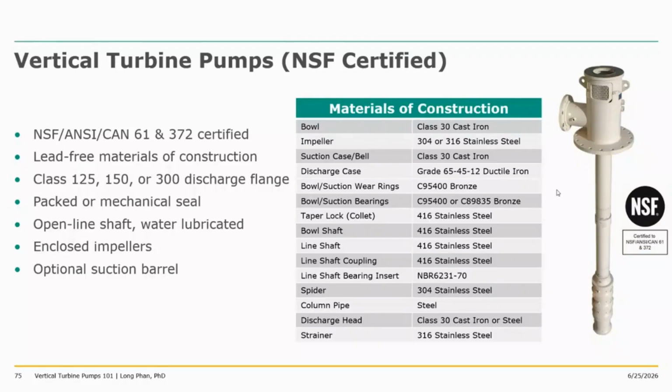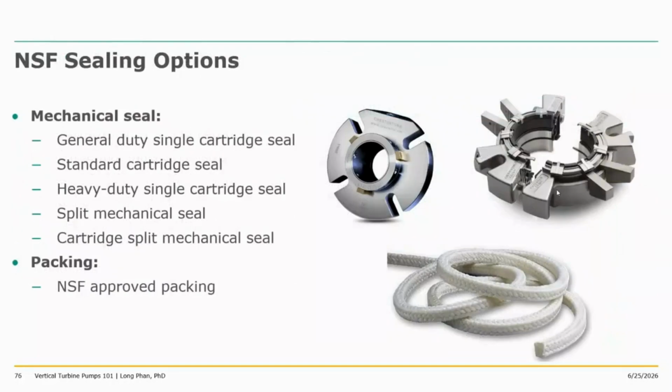Mostly you see stainless steel, which is safe for potable water, or any lead-free bronze. And if you have cast iron or steel in touch with water, you will have a special NSF certified coating for it. And vertical turbine pumps, NSF certified pumps, are great for municipal markets and municipal applications, right? For supporting water to the residents of cities and towns across the globe. They're a subset of vertical turbine, but highly regulated by the NSF agency.